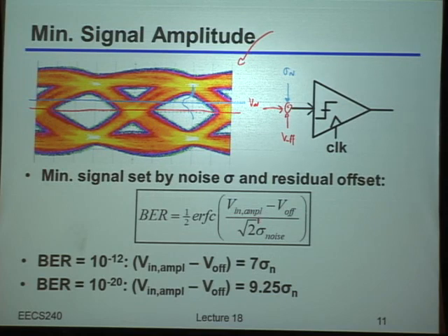What you're essentially going to do is try and figure out how big that is relative to the total area under that noise curve. And the way we figure out that total area is through the so-called complementary error function. Again, we're assuming here it's a Gaussian noise source. So if we want to know the total probability of all of the noise that's larger than this magnitude, you calculate it with the so-called complementary error function. Okay? Yes?